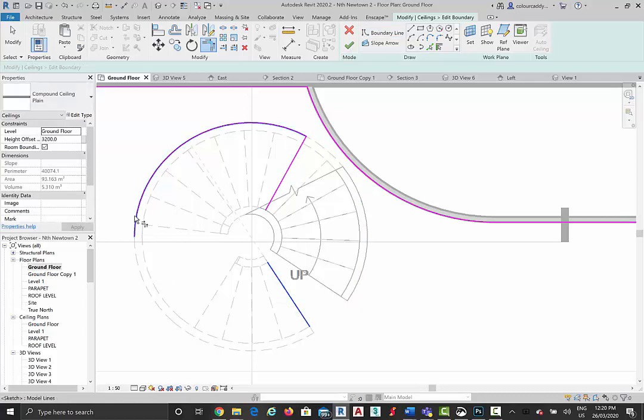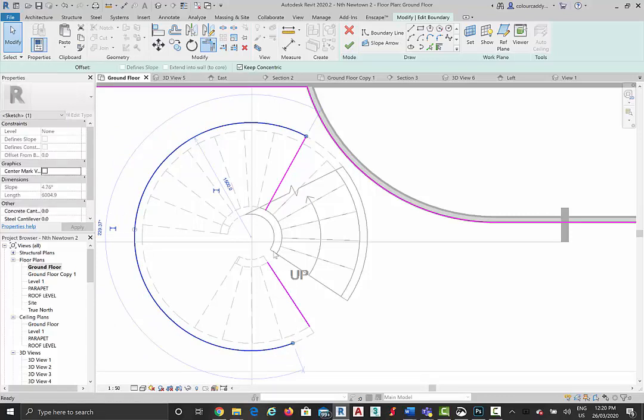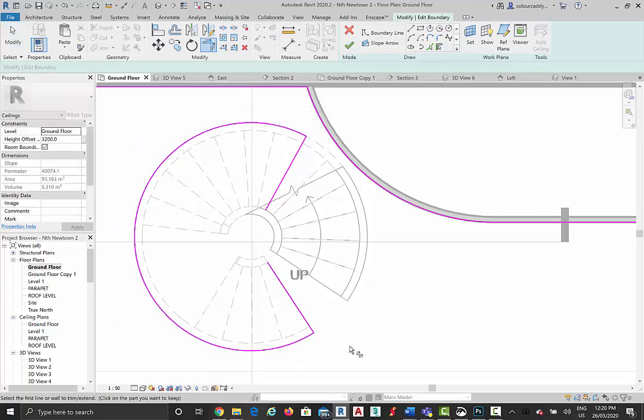Instead of using trim to corner to join those lines together. And this is where it can be a bit frustrating, because the way trim works is that it tries to join to the closest edge, which in this case is at the end that I don't want to change. So there's a simple solution there. When you have an arc like that, you just drag it around so that end is closer to the thing you're trying to join it to. So now that works.